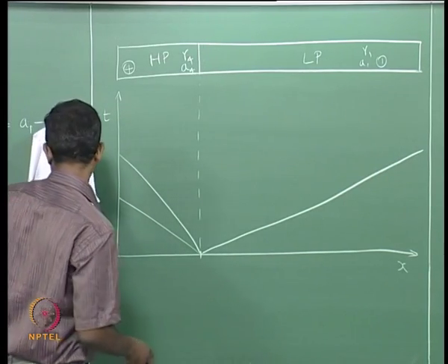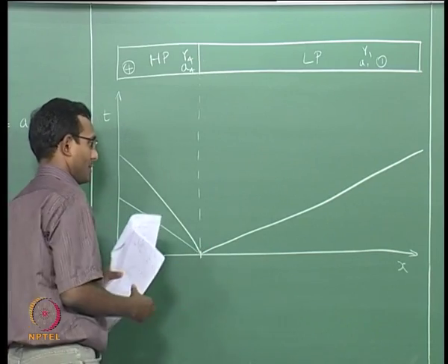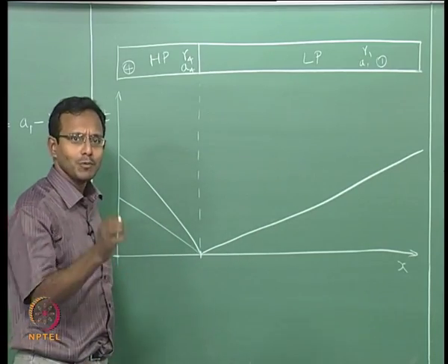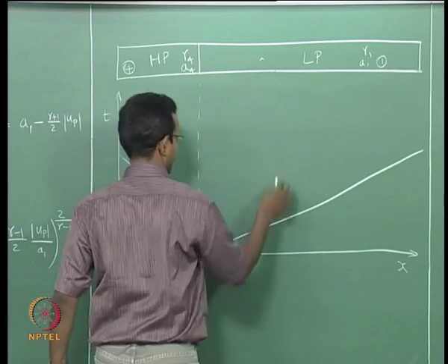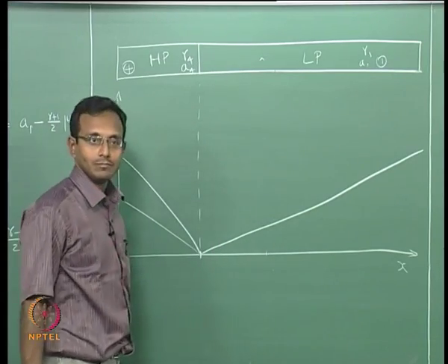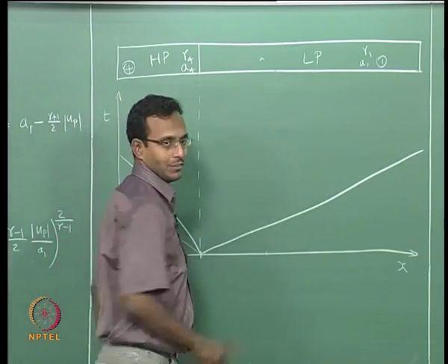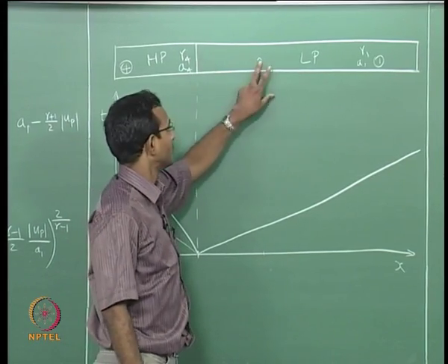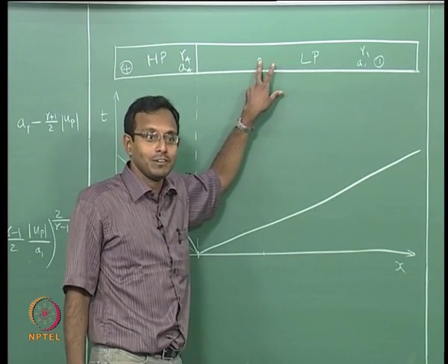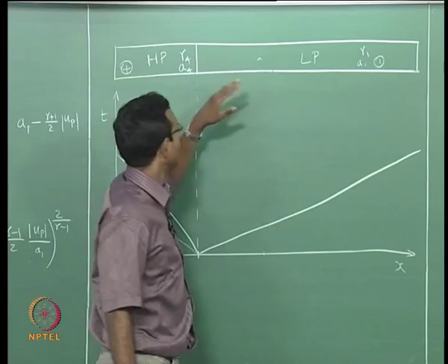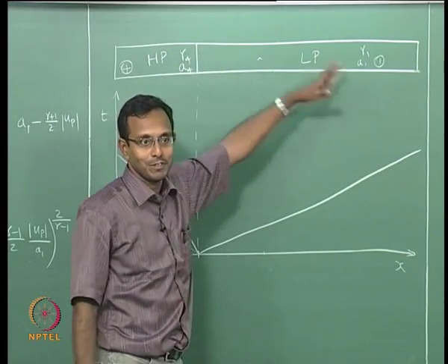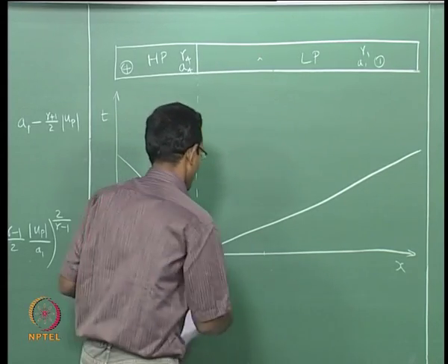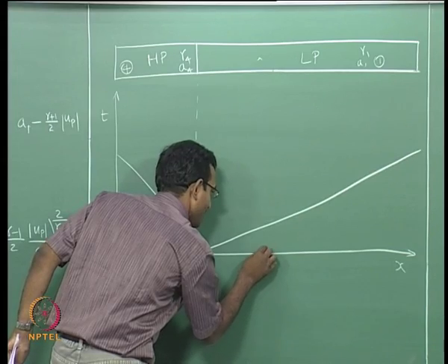Okay. So now if I think about what is happening here, this shock is traveling at this speed. If I think about any particular particle that was sitting at this location, let us say that was here, it is going to be sitting at the same location till some information about this diaphragm breaking comes to this point. What is the first information that comes to that point? It is the shock. Okay, the shock is telling that there is a high pressure section, run away from there. So till that point, that gas element just sits there. So I am going to say it will be sitting there as a function of time.